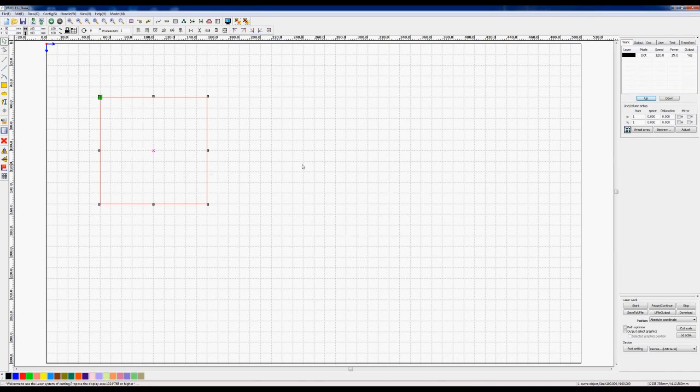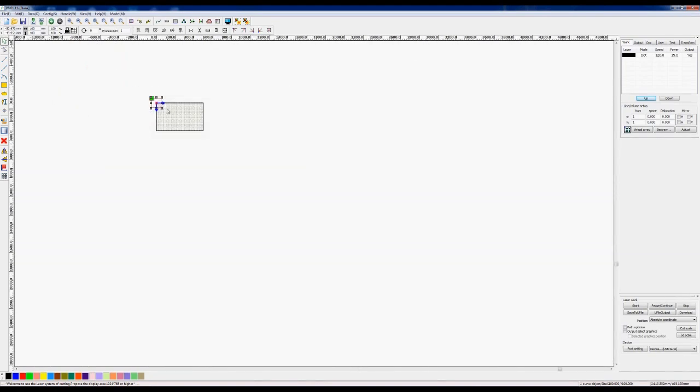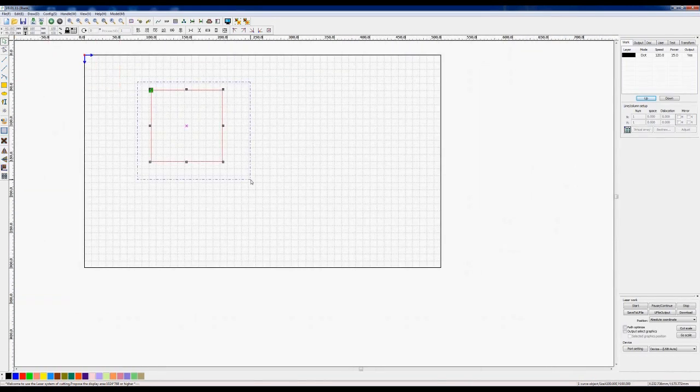Now, I've been using this program for over a year now, and I have never found the need to move that to this corner. There is a danger of having it in the middle with what's about to follow, because if it is in the middle and I finish up moving the center point to 0, like that, look what's happened. Some of the object is outside the work area and the machine won't recognize it. It'll throw a hissy fit. Anyway, let me just reset this again to a correct dimension where I wanted it, which was 50-50, remember now.